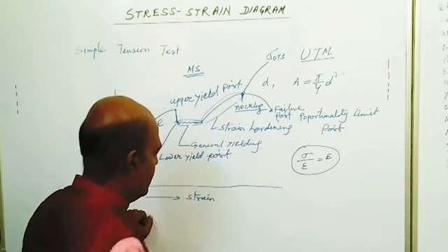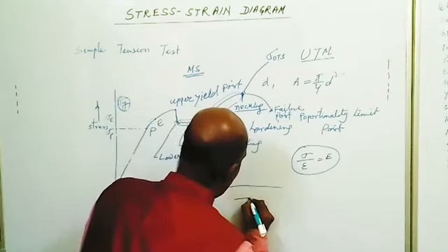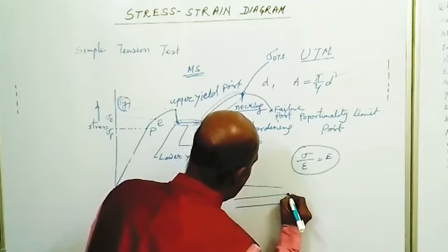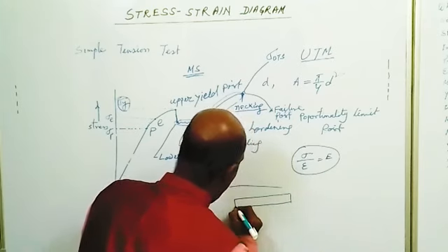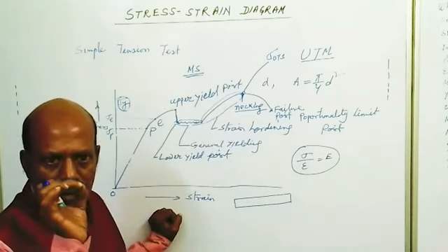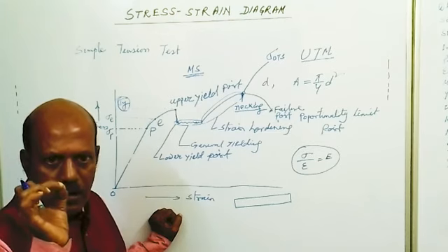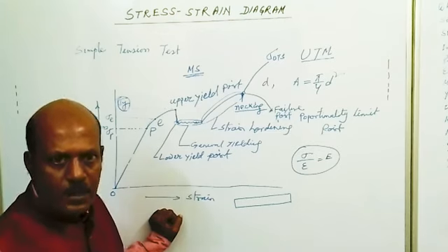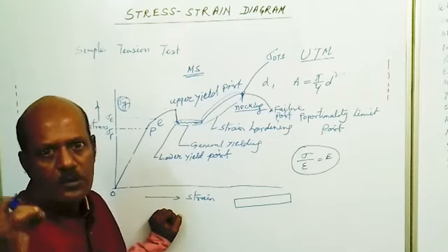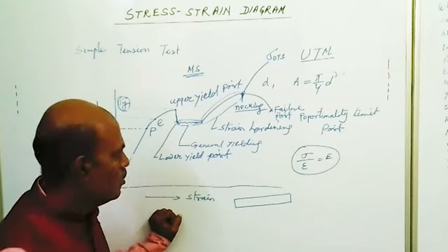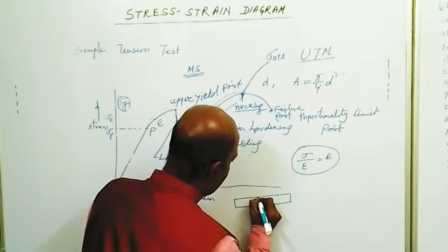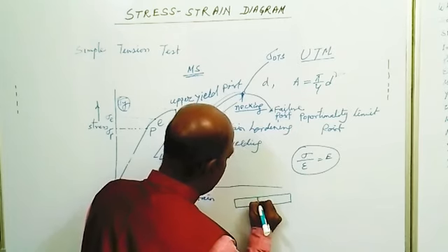What is necking? As per our assumptions, the body is a slender bar, that means all the cross sections of the bar between the gauge length are of equal size. Theoretically it may be possible, but practically it is not possible. So some area may be slightly less than the surrounding area.